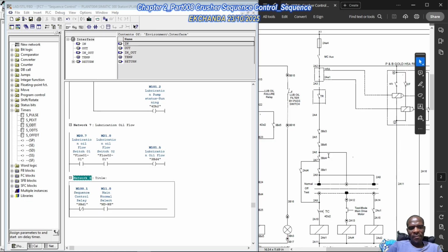But we've said that in the operation of the lubrication pump, if there's no flow by the time the main drive delay timer is timing out, then we're going to trip on level 1 protection, and level 1 protection is a part of 3BD1. So we're good for as long as we've got 3BD1 here, then everything is okay. Whatever this is, we'll just focus on 3BD1, we just depend on 3BD1.